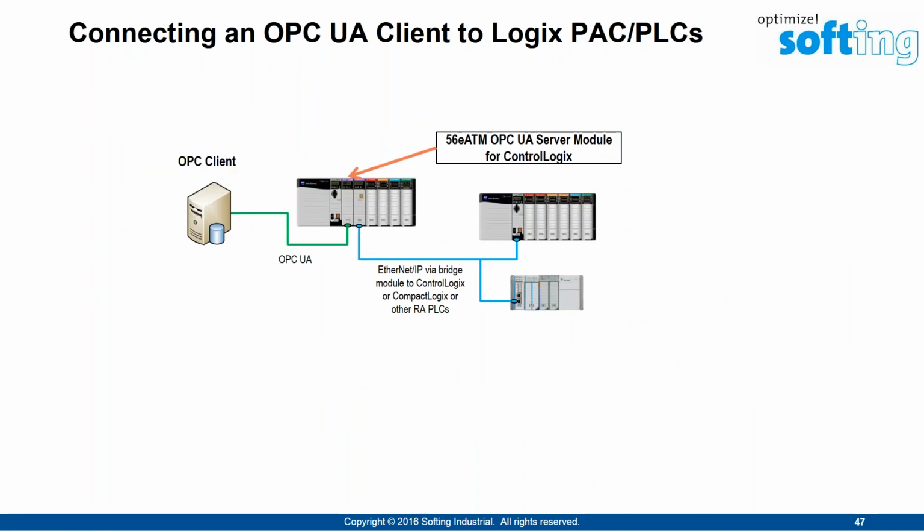Okay, as I mentioned before, the PLC tags are available to the module via the ControlLogix backplane. Also, other controller tags can be accessed via Ethernet IP using one of its Ethernet ports or through an Ethernet IP bridge installed in the same rack. Because the module can access the tags in these ways, there's no need to configure the PLCs to share data amongst each other.